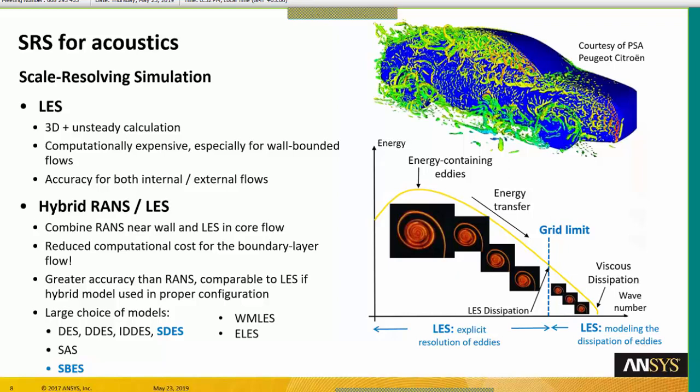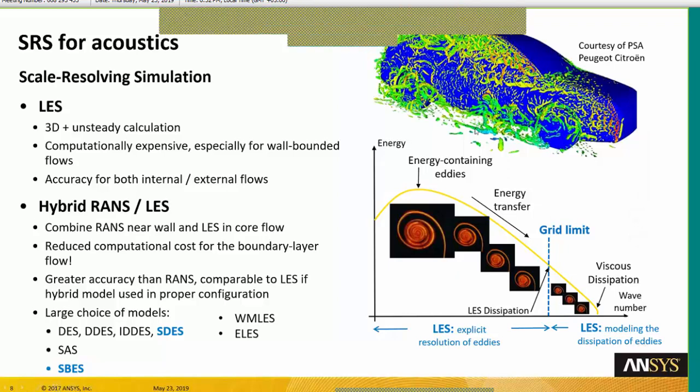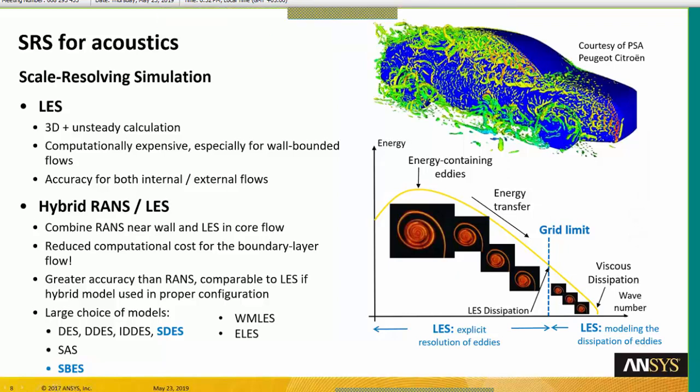All the idea is to properly define this contribution from the RANS up to the LES, to properly feed the turbulent content inside the LES calculation. So here you have an example of a hybrid RANS-LES calculation. You see that you have a large amount of eddies that are created, not everywhere; this creation of eddies is highly anisotropic. And the point is that you are not capturing the eddies that are created near the wall. Near the walls, we completely model the turbulence. We create some turbulence information a bit further from the wall, a bit away from the boundary layer near the wall.